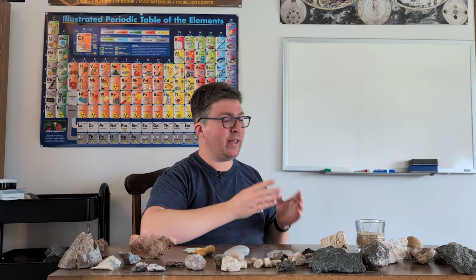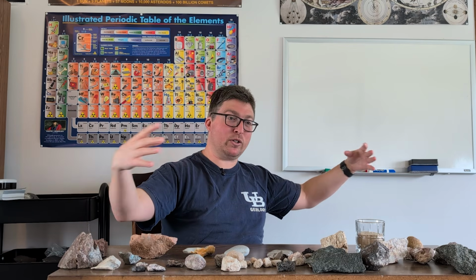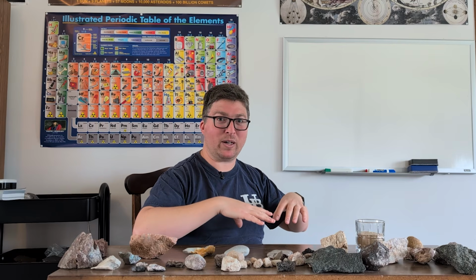Permeability and porosity are also important in digging water wells. If you've got a well on your property, you want it to go into high porosity rock. You want it to hold a lot of water and be able to get a lot of water out. But that doesn't do you any good if the unit that you're drilling into is impermeable. Why is that? Well, if the water can't flow from the surrounding rocks into your well, then your well is going to dry up within a day or two. It's not going to work. You need to be able to draw all the surrounding groundwater into your well.